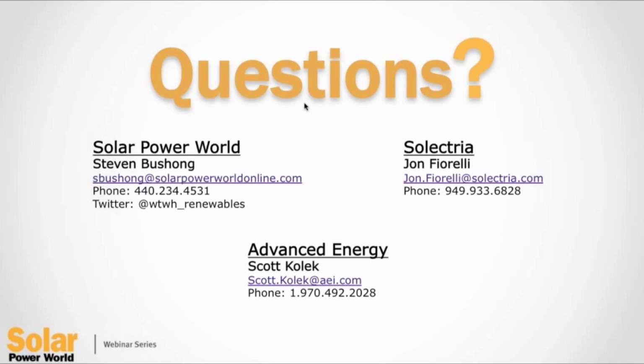Also voltage drop. You want to design to minimize your DC voltage drop to less than 1.5 to 2%, and your AC voltage drop to less than 0.5 to 1%. I think that's a good rule of thumb.